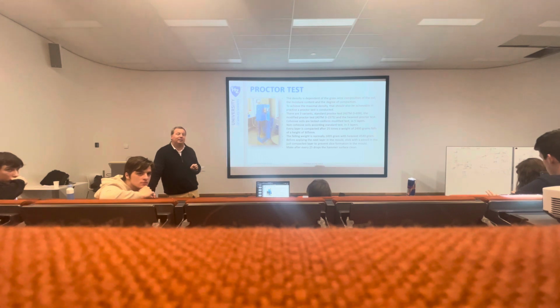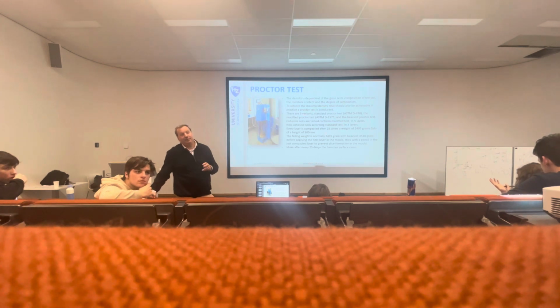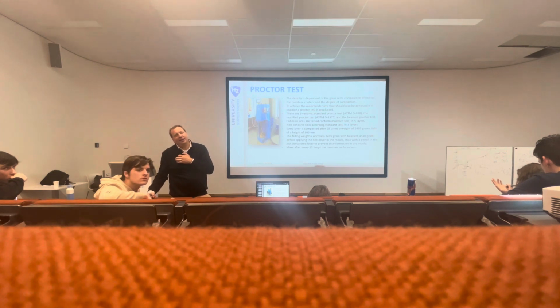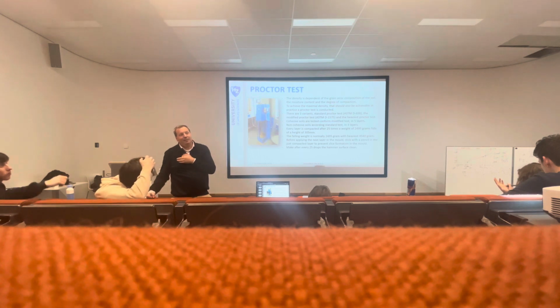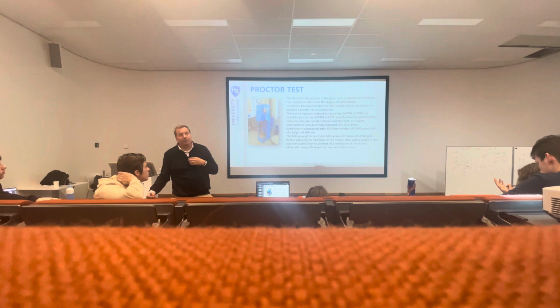So you think that sand is more sensitive to moisture for compaction? It should be more sensitive than clay. For compaction, yeah. Okay, and why? Because the grain size for sands is bigger, and they have more spaces in between. They should be more compactable than clay. Yeah, that's true, you can compact it more. But is it more sensitive when you get a higher moisture content or a lower one than the optimum? That I don't know. Okay, very good.